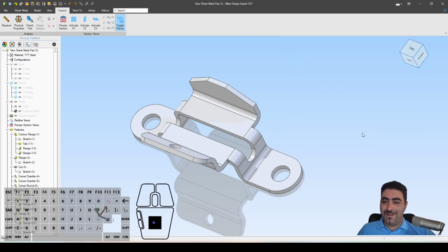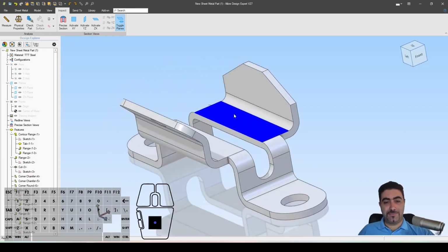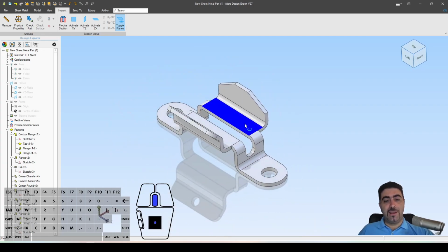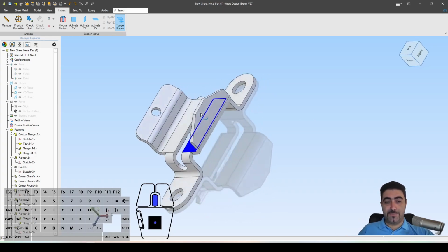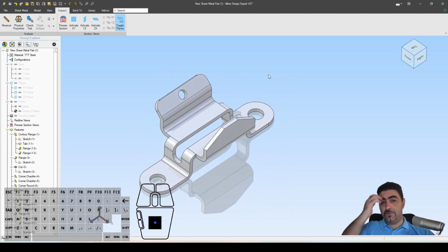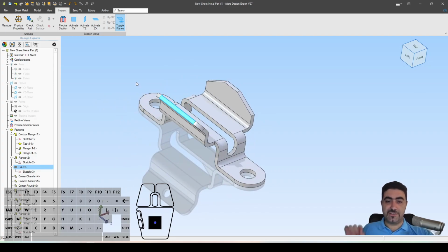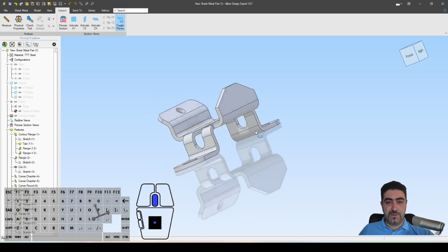Run on your own. Okay, so we saw some really cool tips here. We saw that we should be paying attention always because mistakes cost a lot in sheet metal. We saw how the sheet metal cut works slightly differently to the actual regular extrude cut. It's good practice if you make this model on your own. It's a great sheet metal practice model, actually. And if you do make it on your own, perform this cut here, both with the sheet metal cut and the regular cut. You will see the difference. It's very, very distinctive. It'll be nice to have that as an image in your head, right?